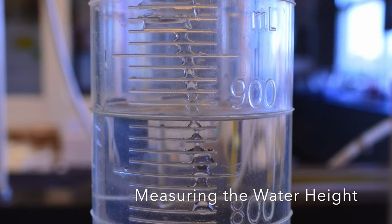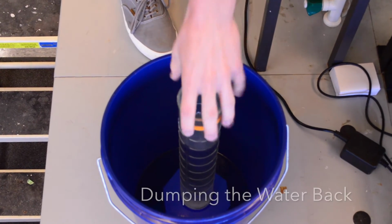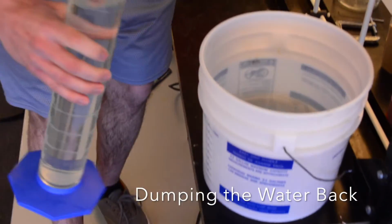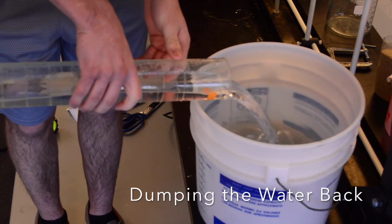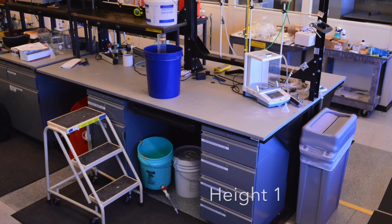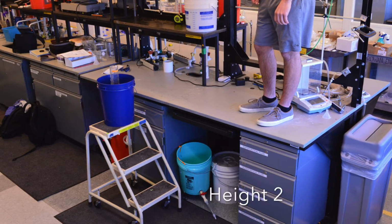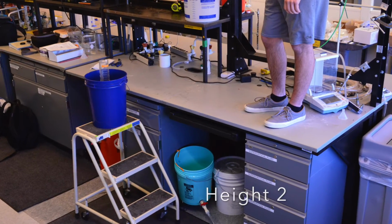Record the volume obtained in the graduated cylinder. Be sure to dump all the water you used back into your bucket after each trial. Run 5 trials at 5 different bucket heights to ensure 5 different flow rates are measured.